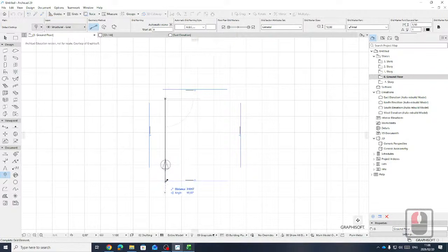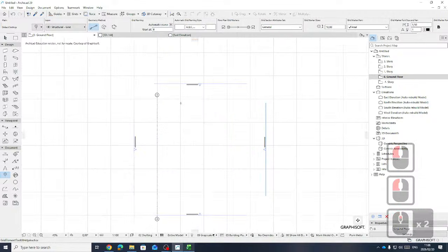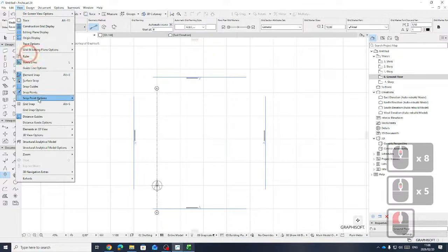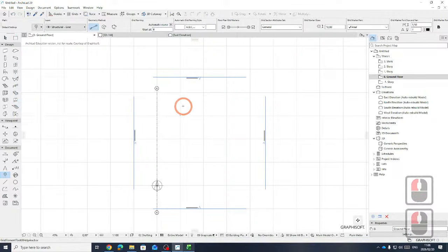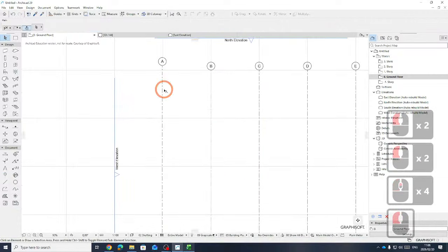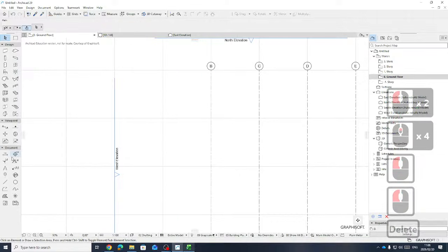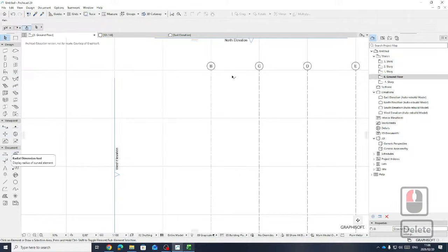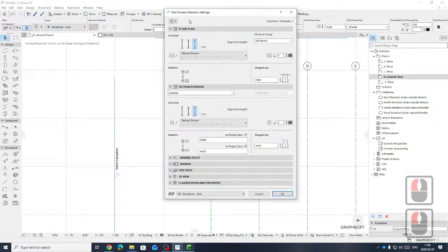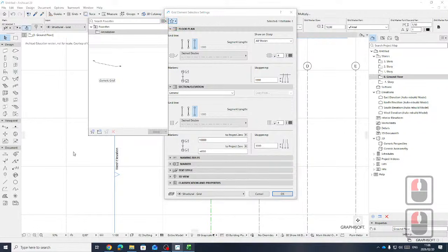And I'm just going to start, I'll take it a bit further. And you'll see that it starts numbering this automatically. Very intuitive. By the way, you must switch it on to snap onto the grid. Okay, there we go. Snap, snap, snap. Very easy. This one I must delete because it was incorrect. Now if you start the grid system again, for those ArchiCAD users, if you want to keep using the same settings, make this a favorite. It's very easy to do.